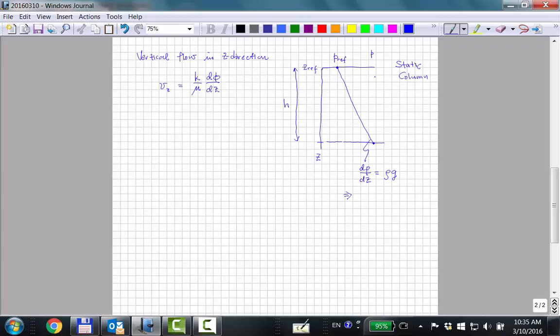Like in a swimming pool. But the water at the bottom of the swimming pool doesn't flow upwards. Not that Darcy's law applies, but if you filled your swimming pool with sand, then you would have Darcy's law applying. And still, the water at the bottom would not flow upwards. Do we agree? It's a static column. What we mean by static column is that the velocity in the z direction is zero. There is no mass transport. There's no movement.